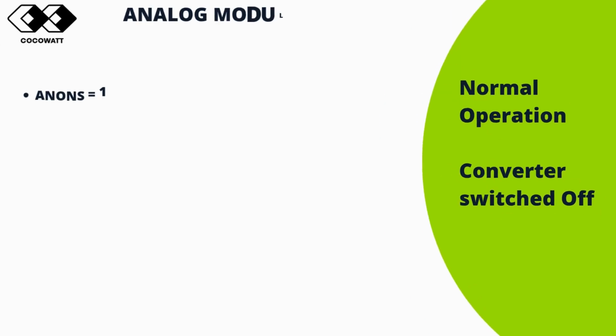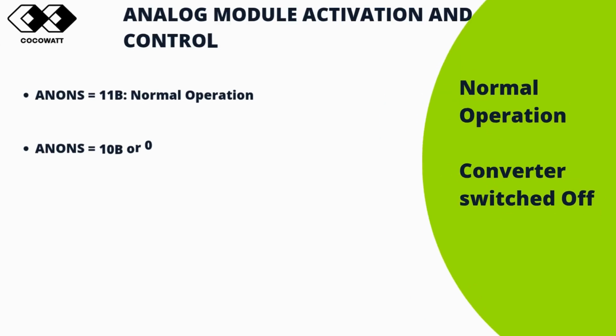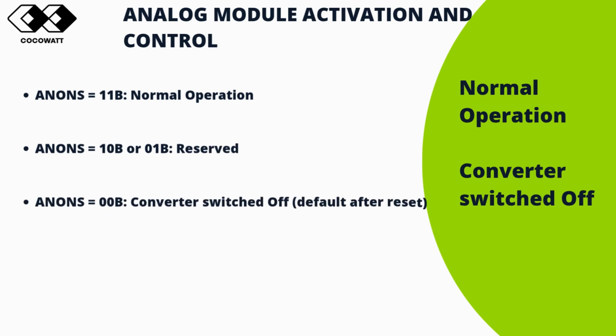The analog converter inside the ADC is the core block responsible for converting the selected input voltage into a digital value. While operating, it continuously draws current, but to save power, it can be turned off between conversions. After a system reset, the analog converters are switched off by default. You must enable them before starting any ADC operation. To ensure accurate conversion, the analog converter can be calibrated to automatically compensate for variation in process, temperature and supply voltage.